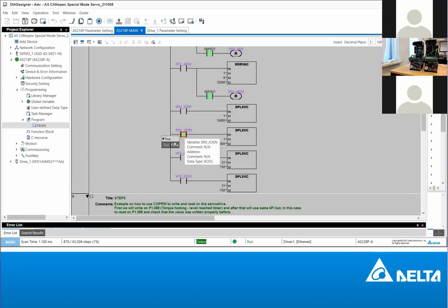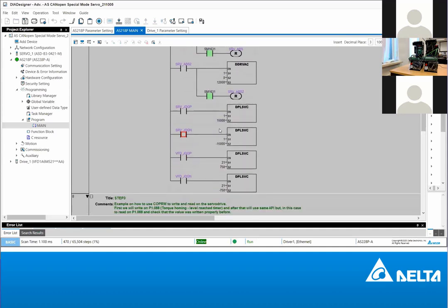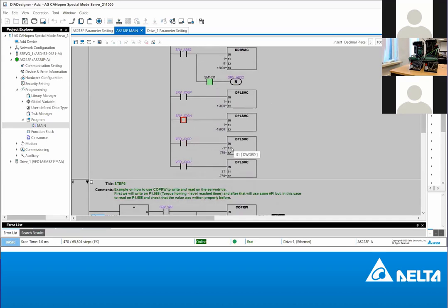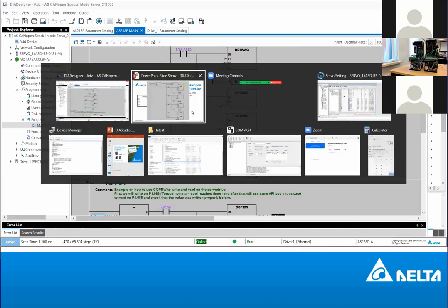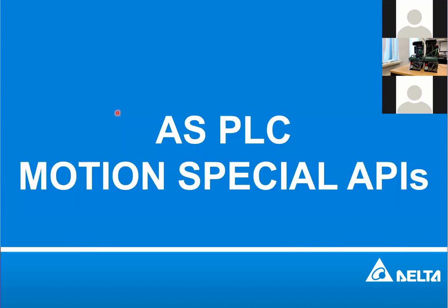Let's stop first. Let's go and choose the slow speed. Okay, it's 1.5. I will trigger this again, but then let's test the inverter. Like you saw when I was doing the setup, there are only 2 possible modes you can choose for the inverter: either speed mode or torque mode.